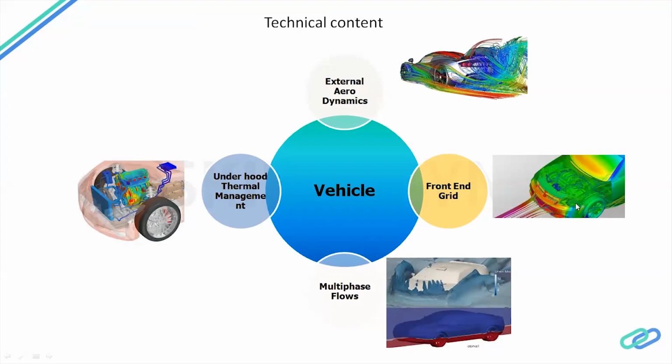This is the second group, front grille analysis. The front grille talks about the bumper openings. We have a vehicle with a bumper. It has some openings where the air will pass through the bumper and through the cooling packs. There is a radiator and condenser inside the vehicle. So here the objective of our people is to improve the mass flow rate towards the radiator and condenser for a given opening area.